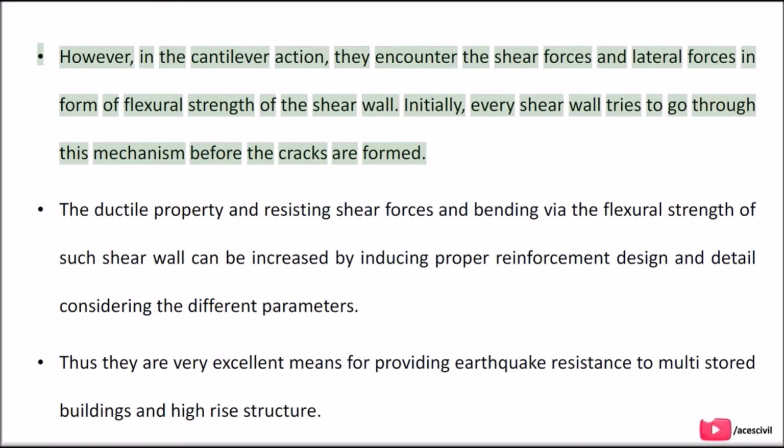However, in the cantilever action, they encounter the shear forces and lateral forces in the form of flexural strength of the shear wall. Initially, every shear wall tries to go through this mechanism before the cracks are formed.